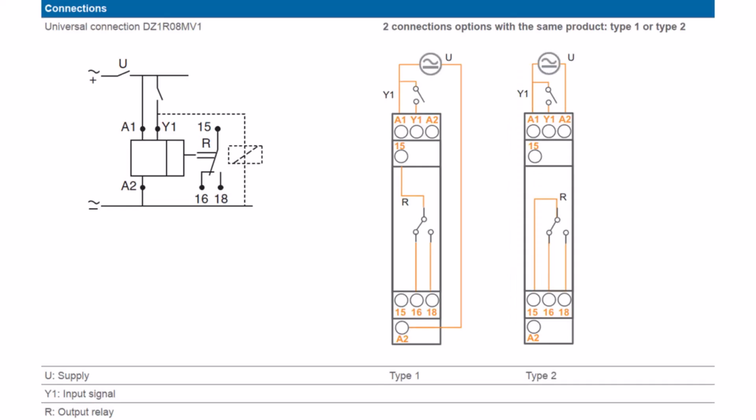Timer documentation shows device pin numbers for the coil, the contacts, and a control contact or input signal connection. This input signal connection is used as a trigger or activation for various timing functions. The input signal connection is not always used.